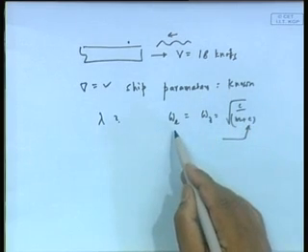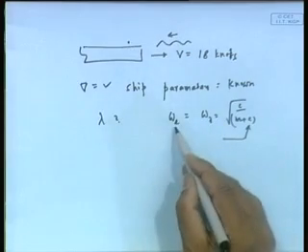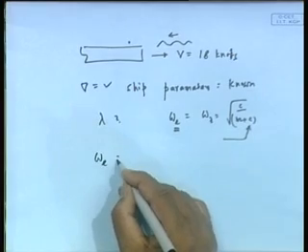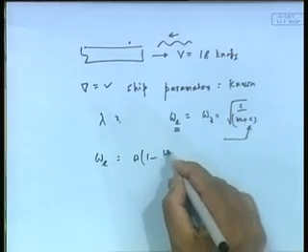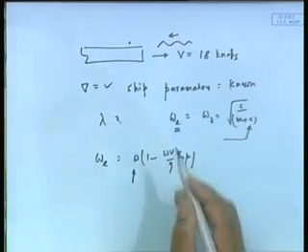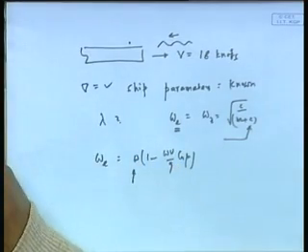From this relation, I will be able to find out the natural period. So, I know what is my omega e. Once I know omega e, I can go back to the relation omega e equal to omega into 1 minus omega V by g cos mu. Mu is given here, so I can find out omega. Once I know omega, I can find out lambda.